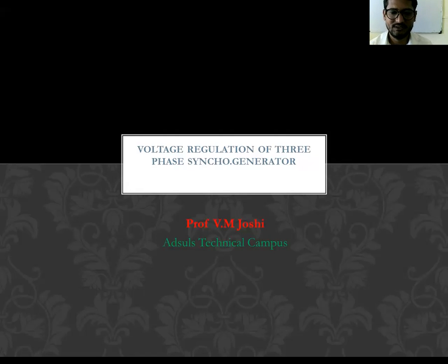Today's lecture we are going to discuss the voltage regulation of a three-phase generator. The voltage regulation is defined as the change in terminal voltage of the alternator when the load is zero, divided by the rated terminal voltage, at a constant speed and excitation. It's called voltage regulation.